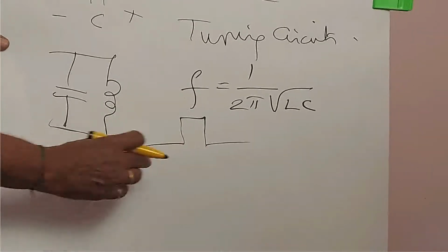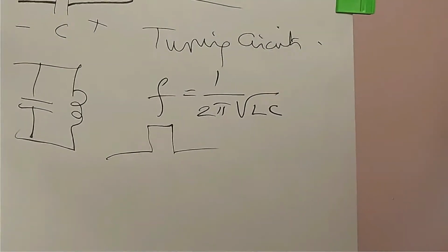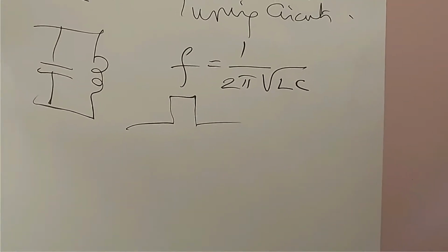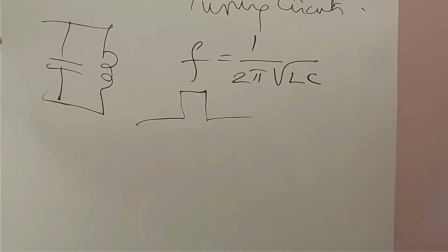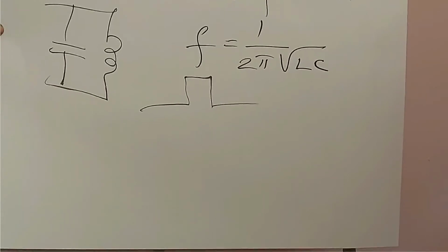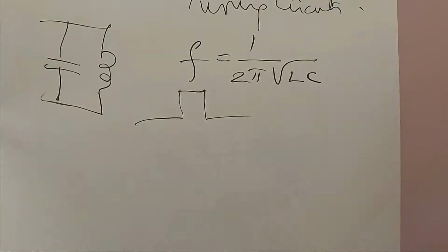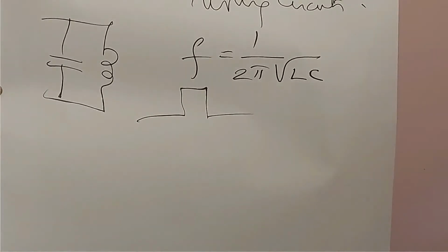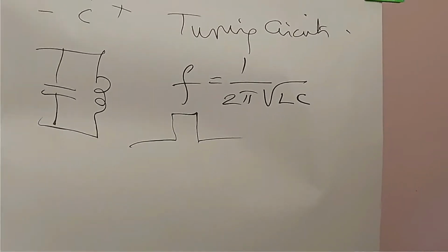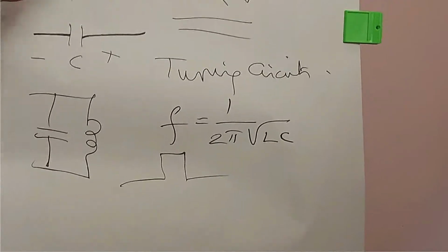The rise time in a circuit is nothing but the time taken by the output to move from 10% to 90%. That is called the rise time. Therefore, this rise time should be small. If it is small, the circuit can be used for many applications. In those cases, a high-speed switching diode can be useful. That diode is called a switching diode.